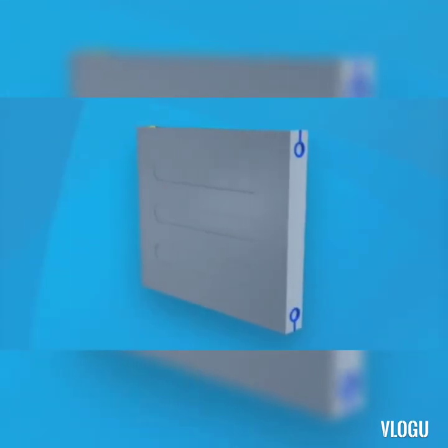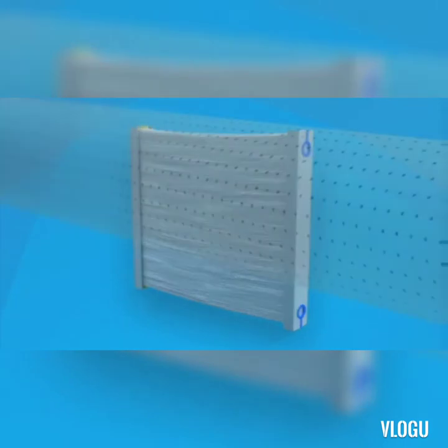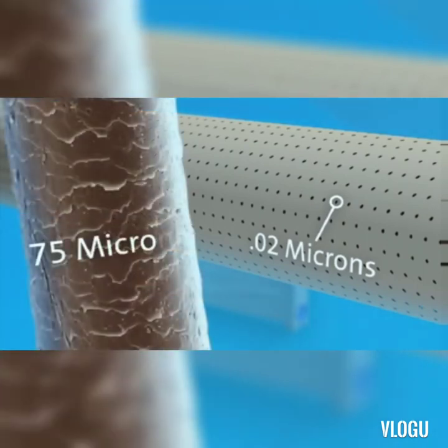The ultrafiltration system at St Mary's uses hollow membrane fibers to remove suspended solids, bacteria and viruses from the tertiary treated wastewater. Each membrane fiber has millions of microscopic pores. Each pore is about 0.02 of a micron in diameter. A human hair is about 75 microns in diameter.